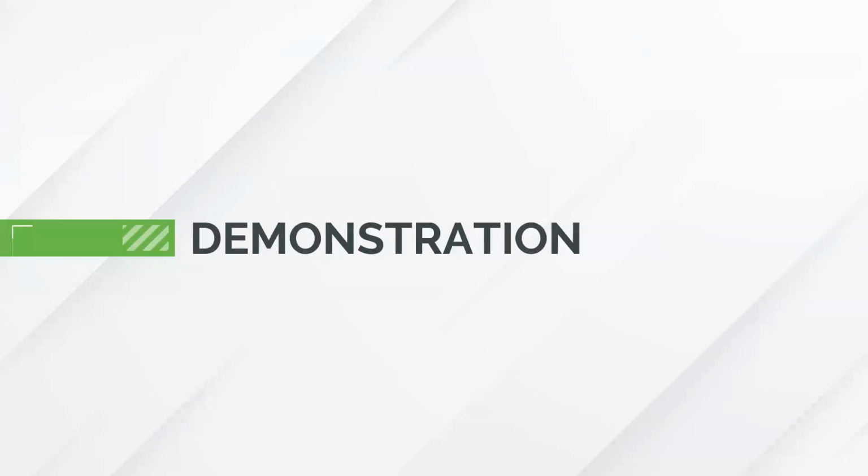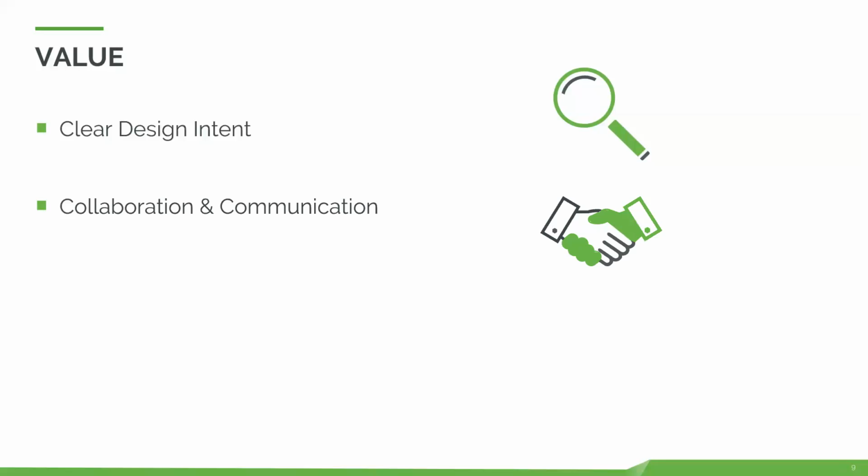I'm going to just wrap up by mentioning some of the main value that we see from some of this. Looking at it from a benefits perspective, first thing being very clear design intent. That's really the main draw of working with model-based definition. It's the fact that you're able to define and lay out 3D annotations in Creo. It's much easier to understand the features and the dimensions that we have in the model. And using tools like GD&T Advisor, you make sure that all the things we're laying out are going to be most accurate, and you're not going to have mistakes that wouldn't have been caught earlier on in the process.